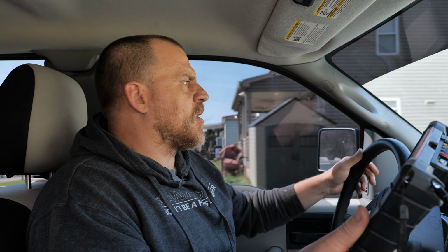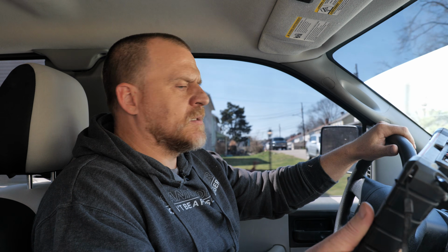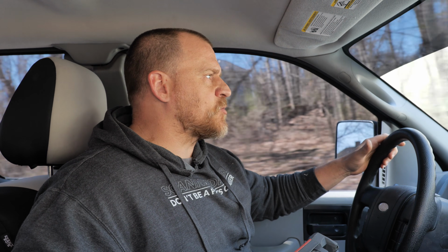We're gonna do a wide open throttle test. You guys have been following along. This is a nice fuel delivery test. We go wide open throttle, we look at our oxygen sensors. We should be rich the whole time we're at wide open throttle. We don't want to see these O2s drop lean. That's what we're looking at.